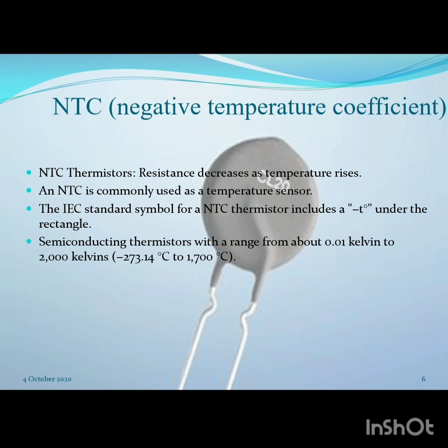Many NTC thermometers are made from a pressed disc, rod, plate, bead or cast chip of semiconducting materials, such as sintered metal oxides. They work because raising the temperature of the semiconductor increases the number of active charge carriers, and it promotes them into the conduction band.